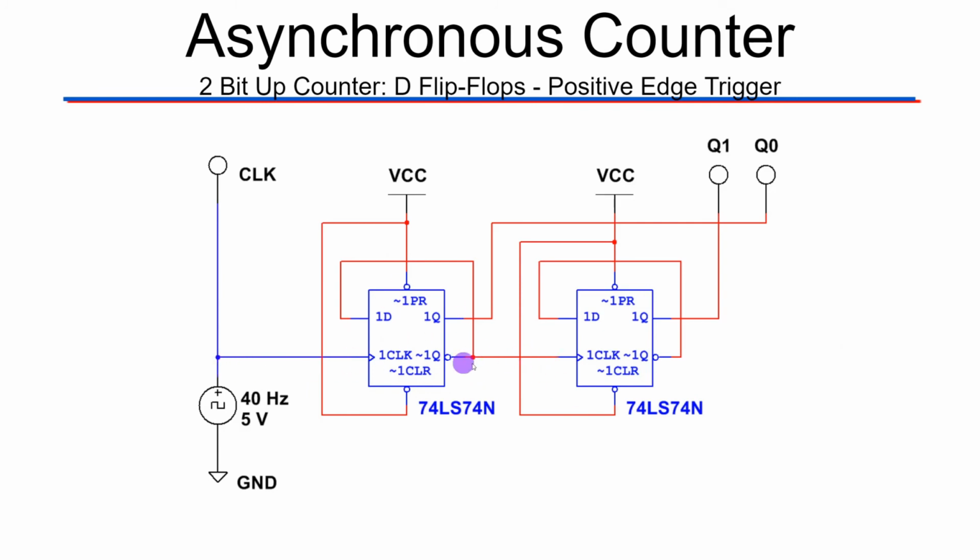All right, and the point is this signal will propagate through our design. So the more flip-flops we add, we're relying on the fact that this clock signal coming in is getting halved every jump between flip-flops, and that is actually what creates our counting behavior.